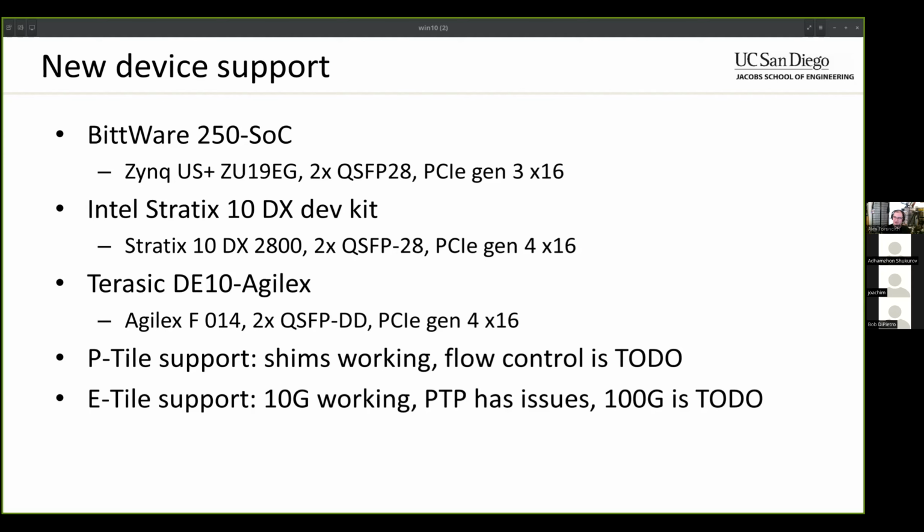Basically, it won't issue any more than, I think the setting is 3 writes for most designs, until it gets a transmit completion sequence number from the hard IP core. And when the DMA engine is directly connected to the IP core, then that's fine. But when you add FIFOs and more pipeline delays and whatnot, that's going to affect the throughput.